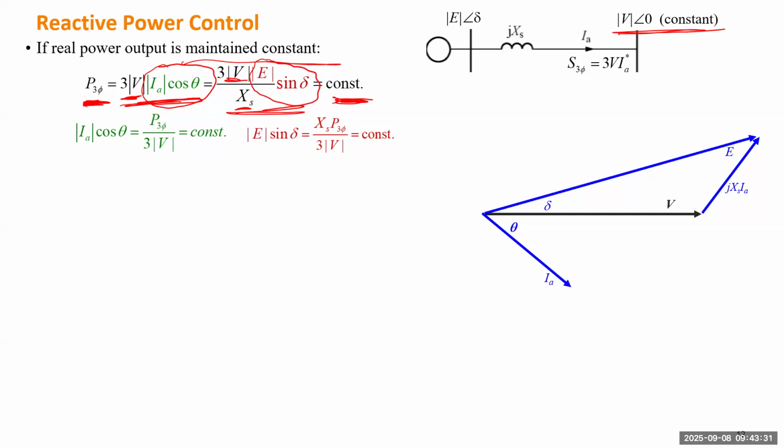So this is the power factor angle to be positive, a lagging power factor. Because it doesn't have any resistance, the voltage drop inside the generator will be mainly on the synchronous reactance. So this phasor is perpendicular to the current and leading the current phasor by 90 degrees.